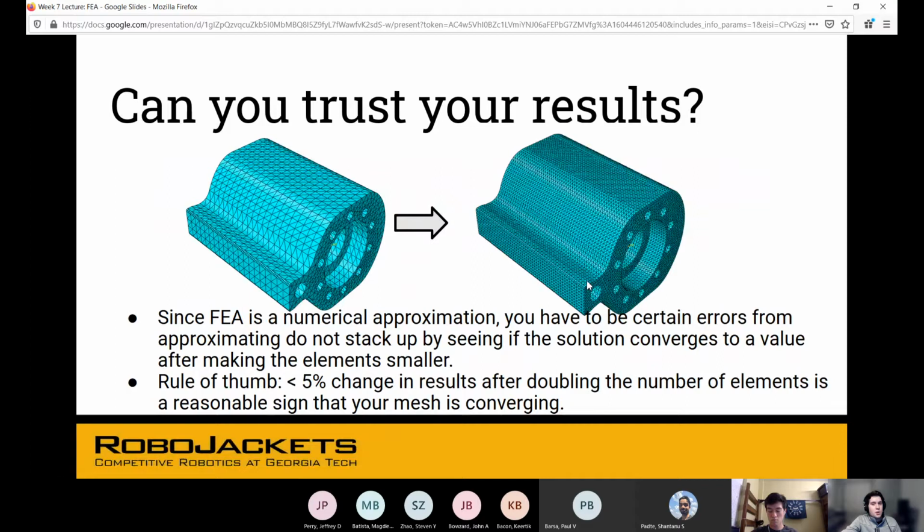One assumption that you could make, that'd be kind of bad, but it's still something that you could do to verify your results, is to consider this portion that's sticking out as a cantilevered beam, right? Then do the hand calc as if it were a cantilevered beam and see what the deflections and stresses are.